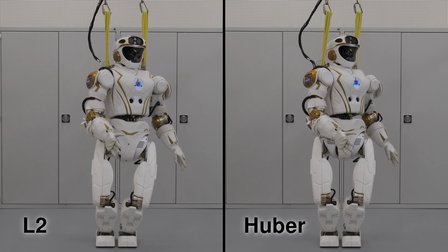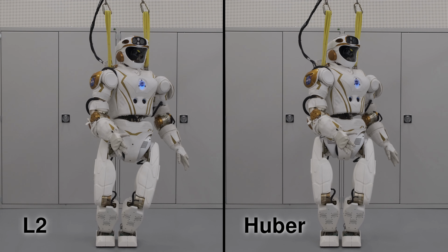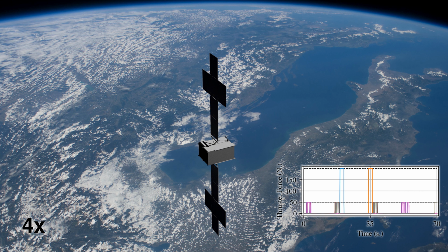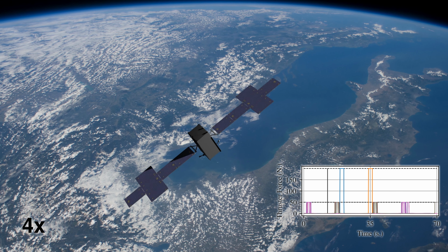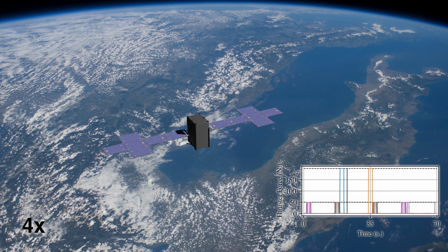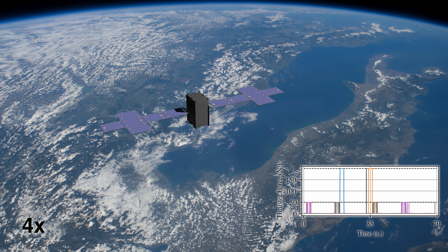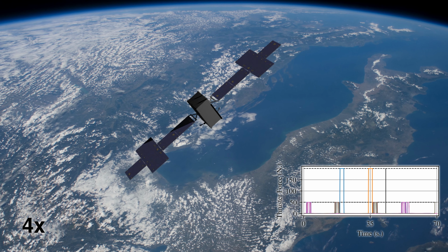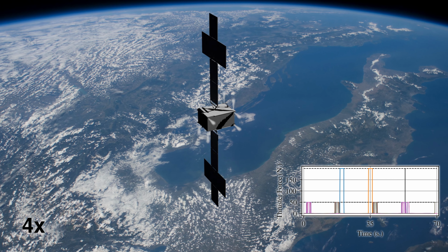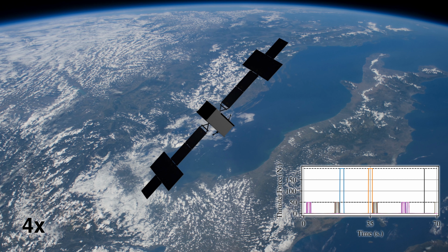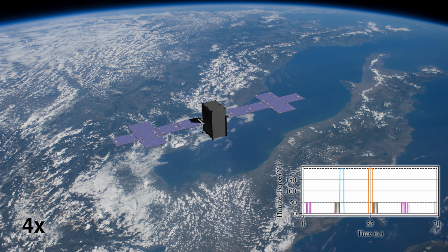We have shown the sparsity-inducing loss function can be used for both joint selection and spacecraft thruster control with the same formulation. On a satellite, we can use the DDP algorithm to plan any feasible sequence of maneuvers by defining a task cost to track a reference trajectory in the state space. Such maneuvers can be used to perform docking or repositioning, which is required for on-orbit construction with a robot arm. The dynamic properties of the spacecraft, any payload, the position of thrusters, and the force these thrusters can generate are taken into account.